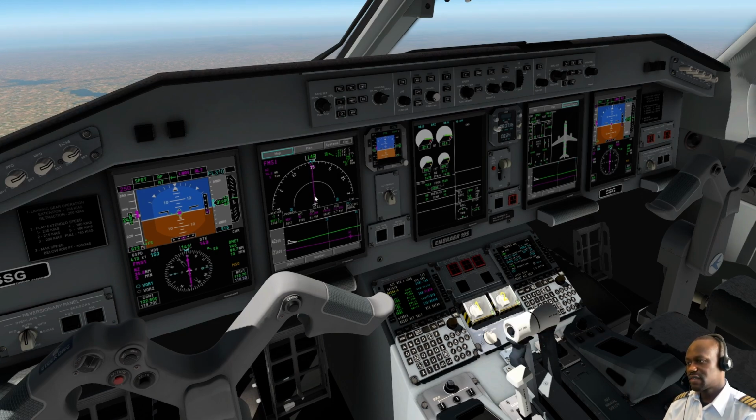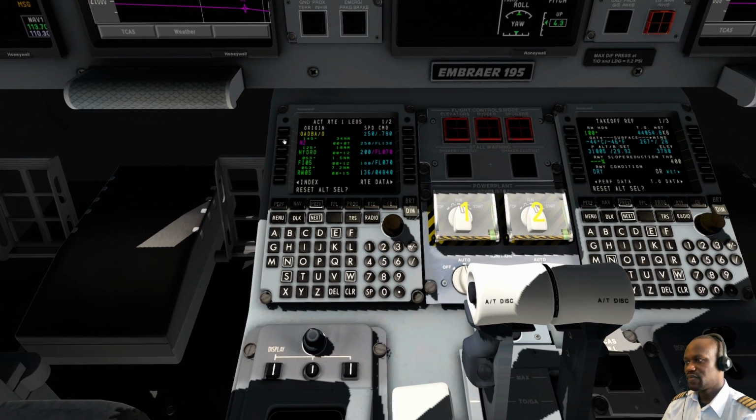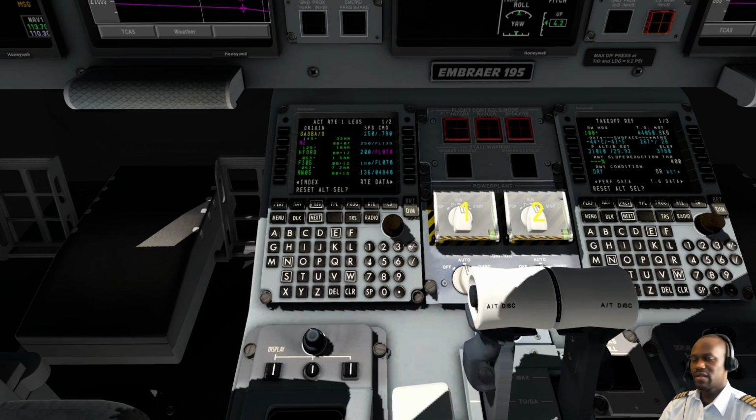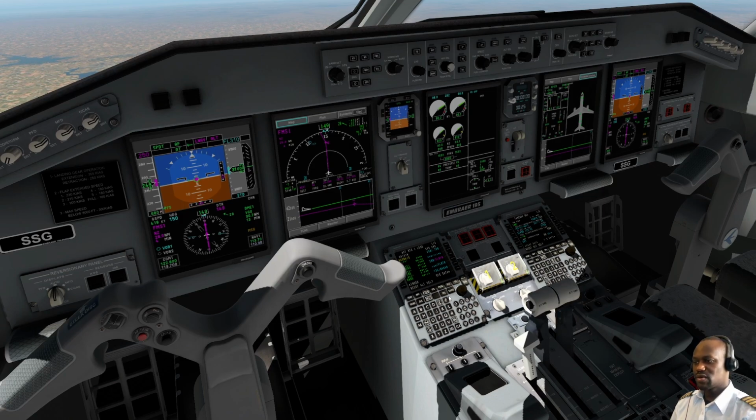So the aircraft will just follow the flight plan. That's November Zulu, Hydro, final approach fix, then to the runway. However, all that will be done at flight level 310. So essentially that's the first warning to the pilots. But the pilots, of course, have not reacted appropriately. It's still indicating reset altitude select. So what I'll do is clear the message so that we can see other messages that come from the FMS through the scratch pad.